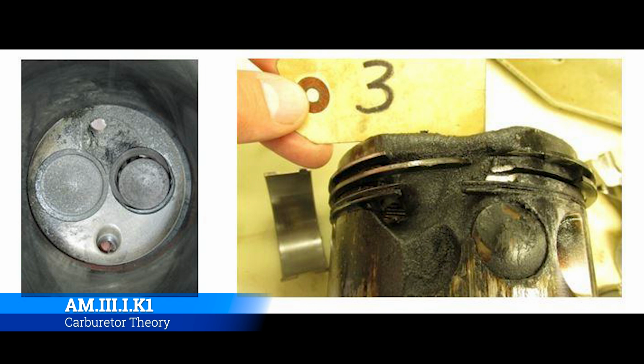And you can see here from these Lycoming pictures what the effects of detonation can be. You see the whole sidewall, the piston is just blown up, burnt down the side. The valve is totally unseated, and it's nothing good. It comes from an engine going through detonation.